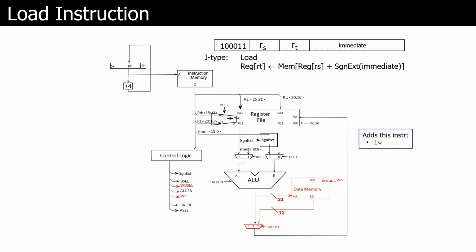And let's think about what we need to actually get instructions out of there. Well, first of all, we need to get the address that we want to look at. And so that's computed and passed through the ALU, and the address we want to look at is sent into data memory. It's then, again, like a lookup table, essentially, where it'll look at the address that you sent into it, it'll get the value out, and that's called register data, or RD.